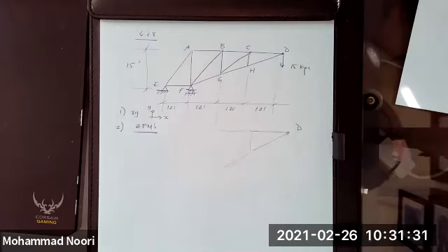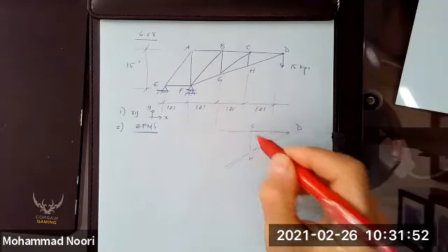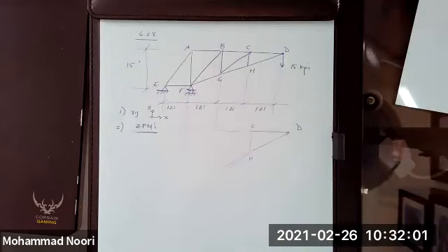Use the concept of zero force members. That's a hint. I'll give you 10 seconds and counting. Well, doesn't the y component of the force HD have to be zero because the sum of all the forces in the y direction are zero? You're getting there. And then the x components of CD and HD have to be the same but opposite? Okay. So what happens?